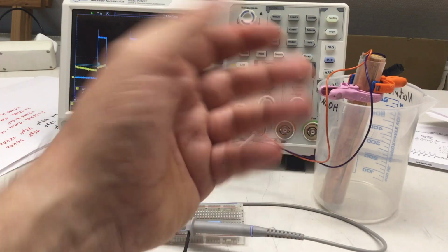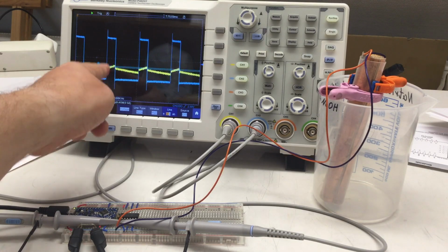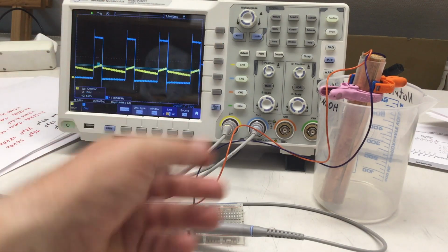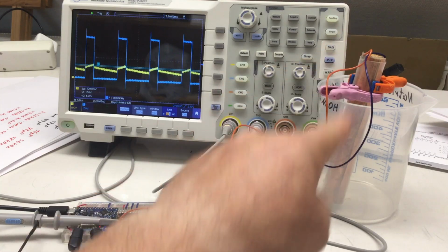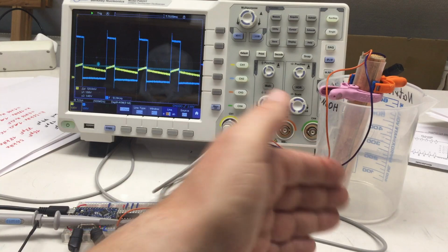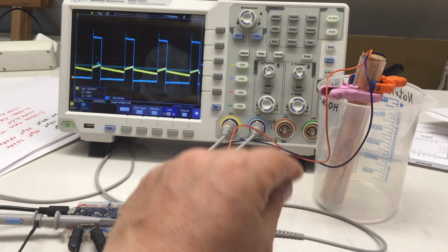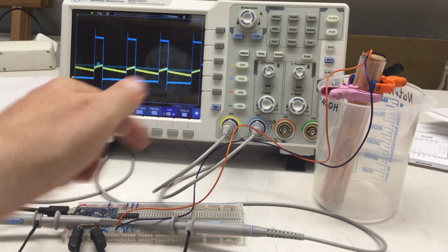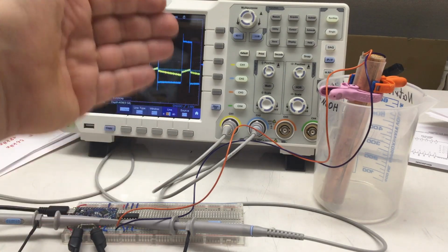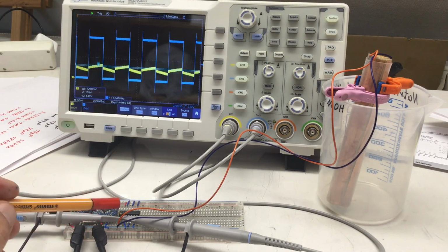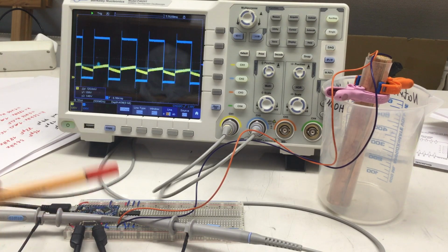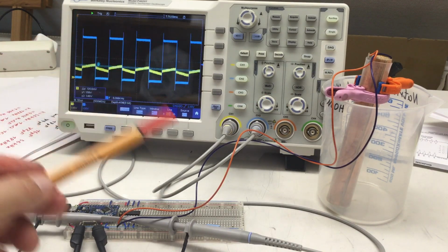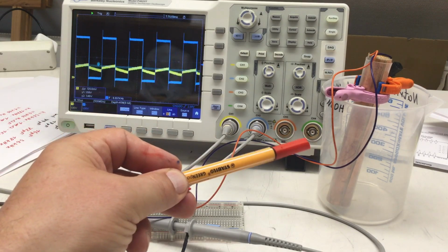But if you are EMI conscious, you notice that the waveform we feed into our antenna, with the hard jumps and so on, will create a lot of high frequency harmonics. And so that thing is actually transmitting when we run it at higher frequencies. To minimize that, we should lower the frequency. So let's try some larger capacitor resistors here to lower the frequency a bit. I replaced my 1 megaohm resistor with a 10 megaohm resistor, and I changed the time scale; we are now down to 6 kilohertz. I feel much more comfortable with that EMI-wise.